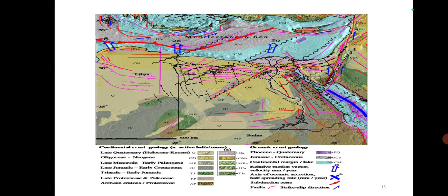We can identify such zones and plan land use, limiting constructions in areas where minimum pressure should be given to the land. All those construction activities can be limited in potentially dangerous zones of seismic activity. So this is the use of this structural map and also topo sheets.